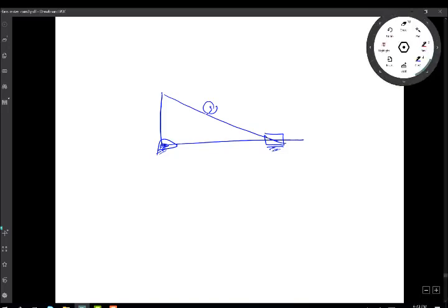Okay, so now I have here link number 2, link 3, and link number 4. This point here, as before, is point number 3, 4. And this point is 2, 3. And this point is 1, 3, the obvious ones. To get the common point between 4 and 1, I draw a perpendicular like that.